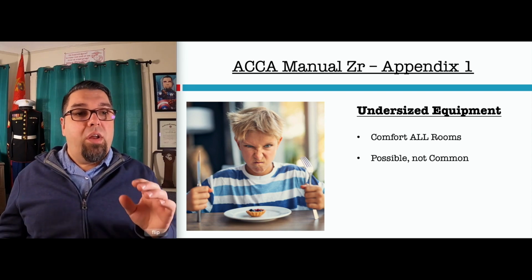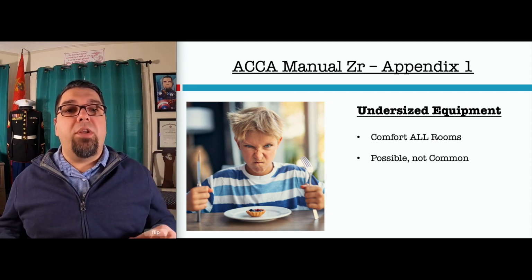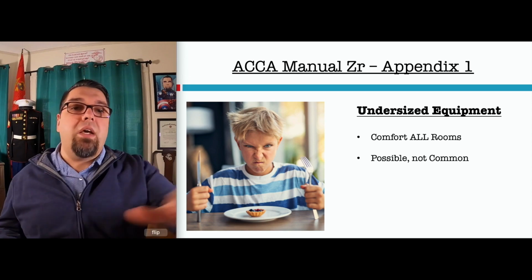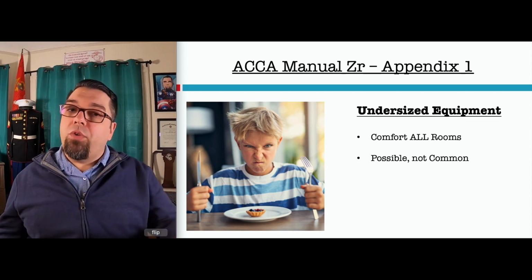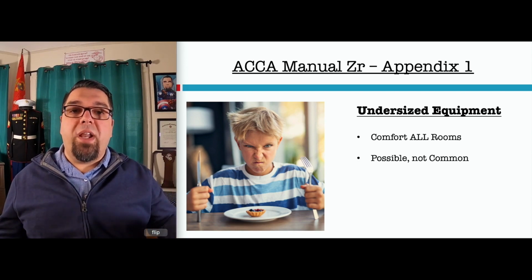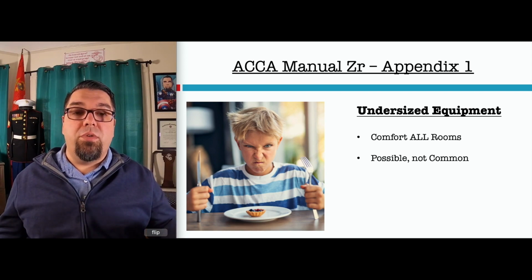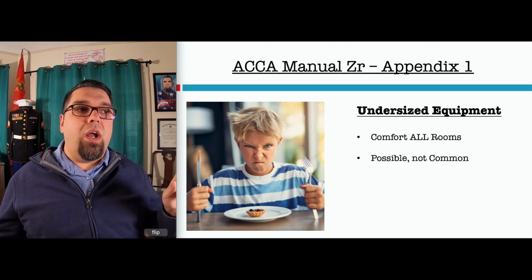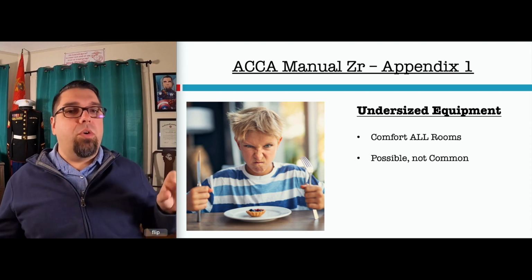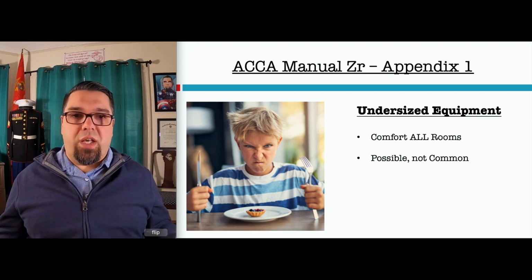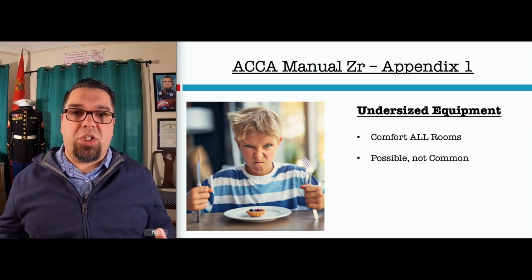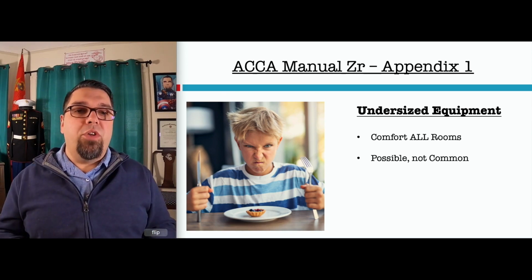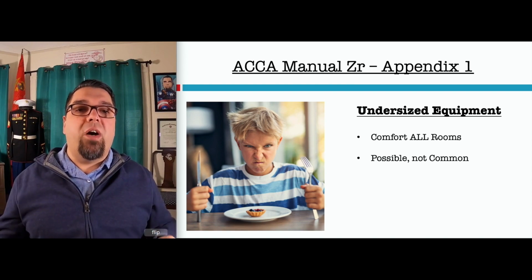Think about what's going to happen here. If you have undersized equipment, you're not going to have comfort in any of the rooms. All of the rooms, when you're at or above design temperatures, are not going to be comfortable. It's not one room. If it's one room, then you might have a design issue when it comes to your duct size or air sealing or balancing or something along those lines, right? Or just the way the system was set up, the way it was commissioned. You didn't set it up for the right airflow. There's all kinds of possibilities why you don't have comfort in one room.